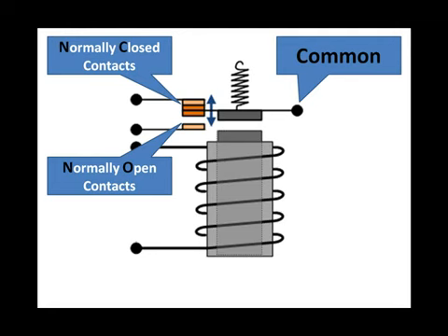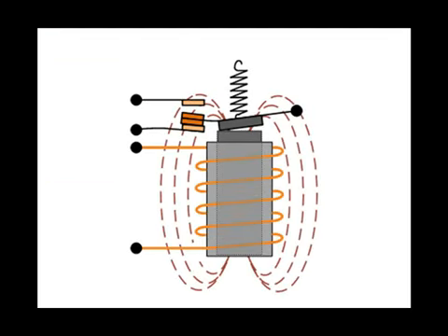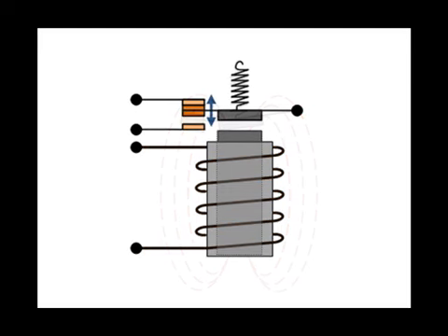When this coil is energized, the resulting magnetic field attracts the armature towards the pole piece of the coil, overcoming the spring tension to open one set of switch contacts and then closes another set of contacts as the armature reaches the end of travel. As long as the coil remains energized, these contacts are held closed. When the coil is de-energized, the spring tension opens this set of switch contacts, and consequently at the end of the spring travel closes another set of contacts.